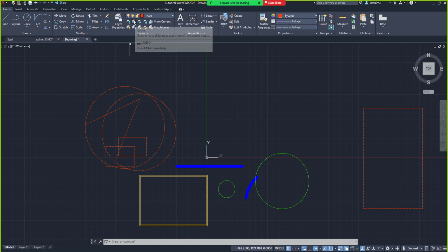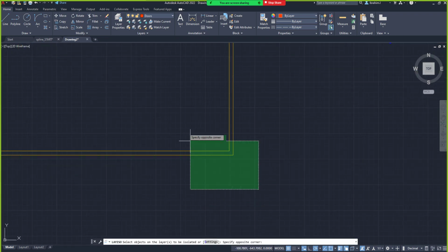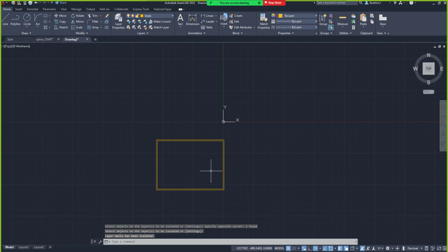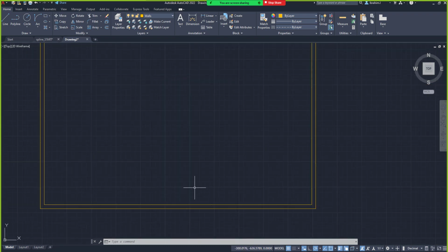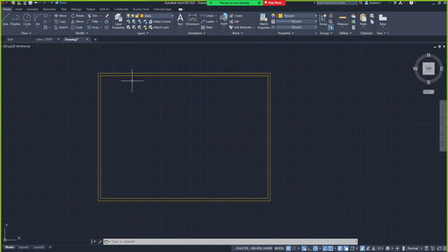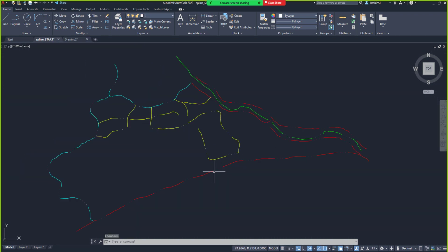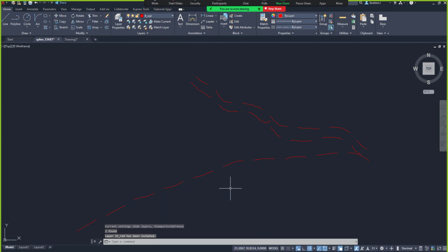The next one that we have here is called the what? Isolate. When you use the isolate command, for example, let me isolate our wall here. I'll go to isolate and then I'll select our wall here. What will happen when I click on enter is that every other layer will be taken off, except that layer that I want to work on. Sometimes your design is loaded. You have a lot of things on your screen, so you want to isolate a particular layer. All you need to do is select the particular layer that you want to see, and then you isolate. Are you with me?